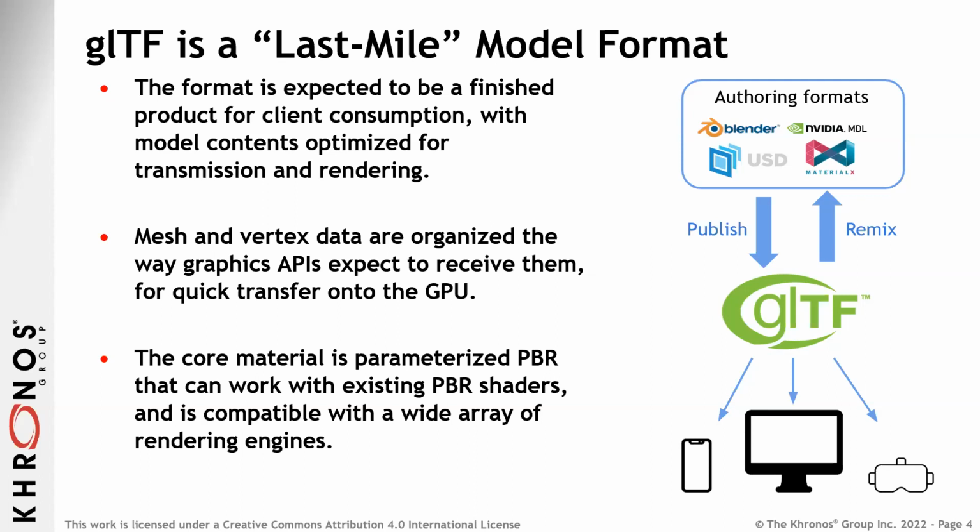The act of publishing it to glTF changes the nature of the data that's stored. It's no longer organized the way it would be for an artist to continue editing the model. And instead, it's packed in more closer to the way that a consumer GPU would need to render that data more immediately. And that has implications for our material model. We don't necessarily want your average glTF file to have a fancy MaterialX set of 1,000 shader nodes and then deliver that onto some mobile phone with some battery operated GPU and ask it to render such a sophisticated shader. We can get in trouble that way very quickly.